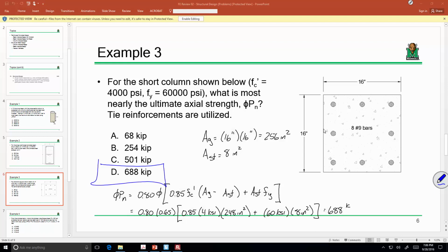Now, if you've had reinforced concrete design, was that a simple one? A lot of those types of conceptual questions are going to be a piece of cake if you've had any of these classes. Let me give you the background on that question. Development length is how far you need to encase a piece of rebar into concrete in order to develop its full capacity.